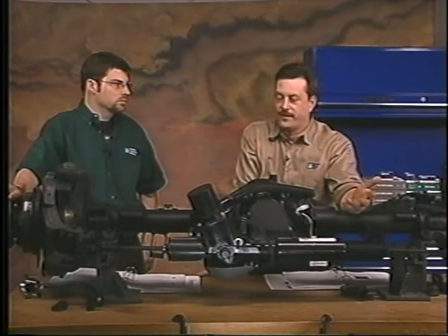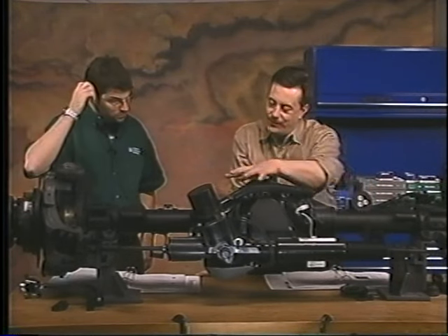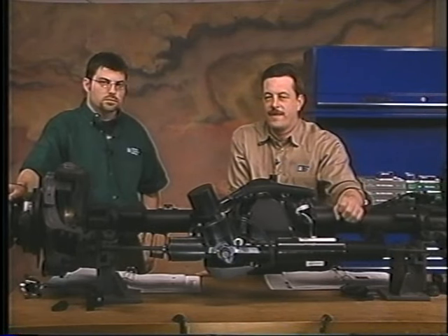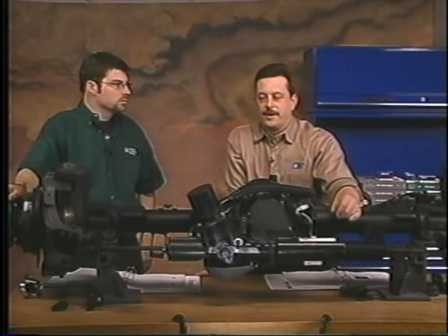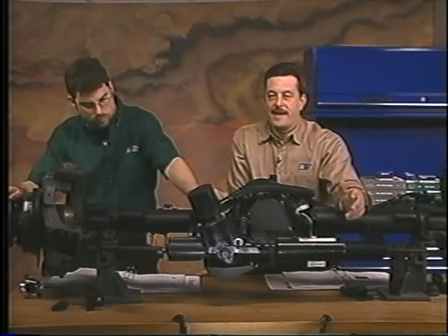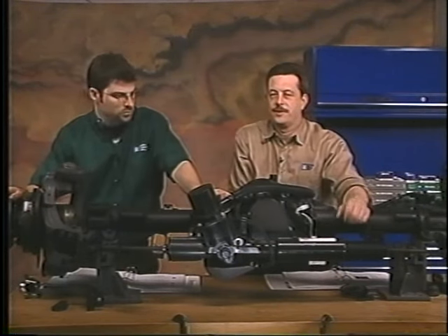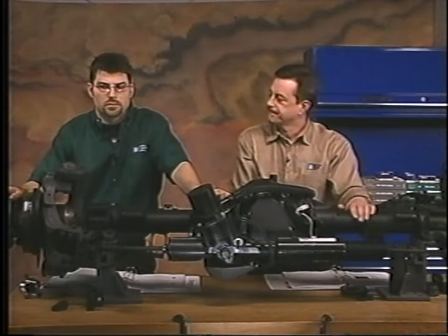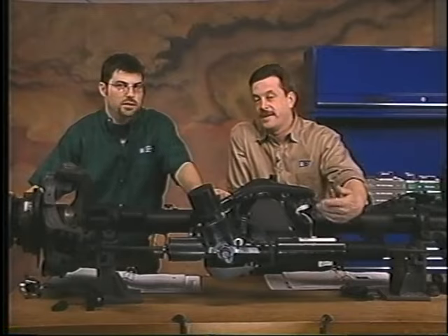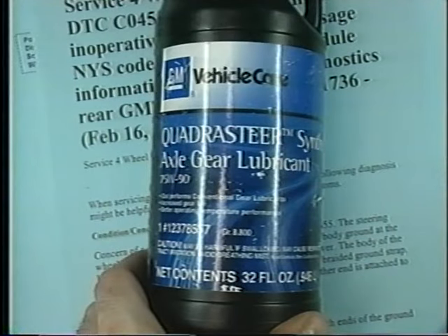So to drain that fluid out and fill it back up, you don't even have to take the cover off at all. So you don't have to deal with any of this. Now, it is a synthetic fluid. There is a specific part number for that, and you should look that up in the parts department. Now, that synthetic fluid already has the friction modifier added into it. So it's nothing to add, just pour it in, takes about 3 of those containers to fill things up here. Okay? But it is specific. It is specific for this Quadrasteer system. Yeah, we got that on the overhead right now. Take a quick look. There it is. Quadrasteer synthetic axle gear lubricant. So definitely what you want to use. You don't need to use regular fluid at all.